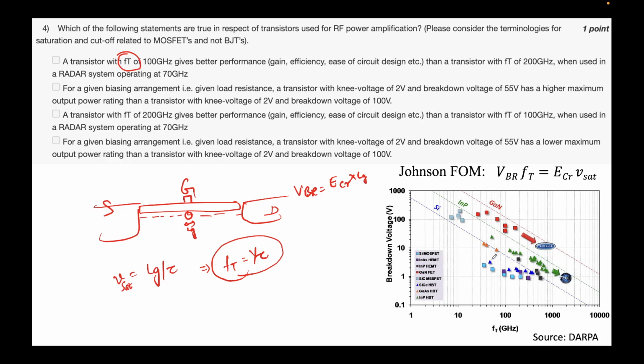And but you can also see, as I was saying in the previous slide, that for silicon they're very close to the theoretical limit, but there's still some gap to go between the experimental results, which are squares here, and the theoretical limit for gallium nitride. So that's when a technology matures. That's how it comes. So the devices that we typically get for silicon are your HBTs, and HBTs are also there for indium phosphide as well.